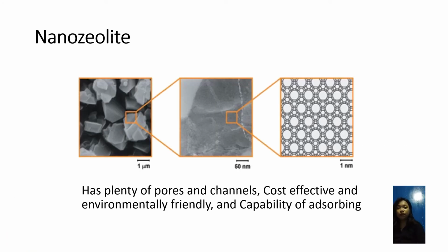So polymers can be improved by adding fillers, and one of the most promising filler materials for improving dye removal in wastewater is nanozeolite. Nanozeolites have been discovered to be more efficient in wastewater treatment than micro-sized zeolites. This is because nanozeolites have a higher surface area and surface active sites, as well as the ability to be reused. Due to the increasing problem in aqueous solutions, some researchers investigate the removal of heavy metals and dyes with the use of nanozeolite.